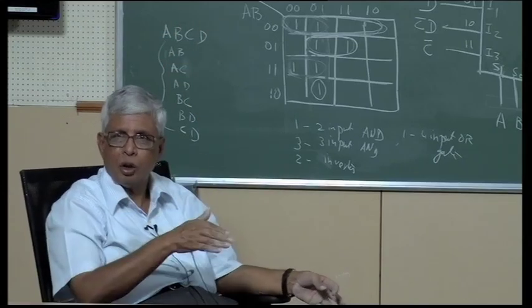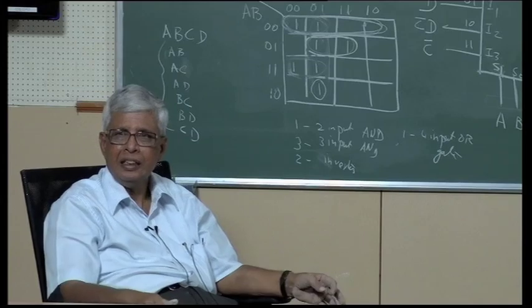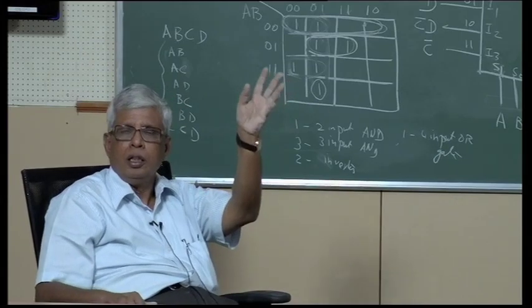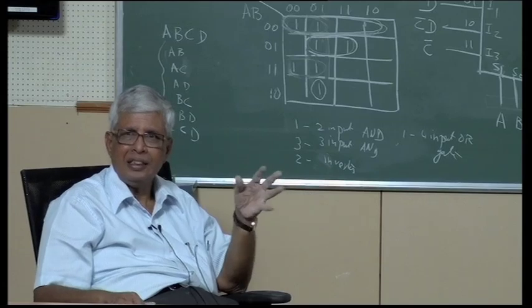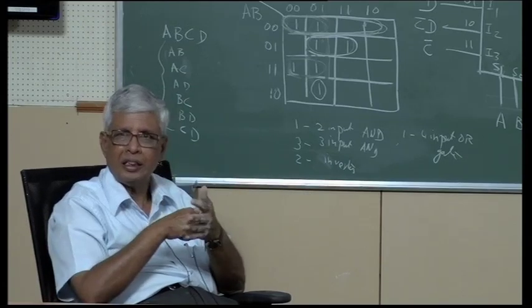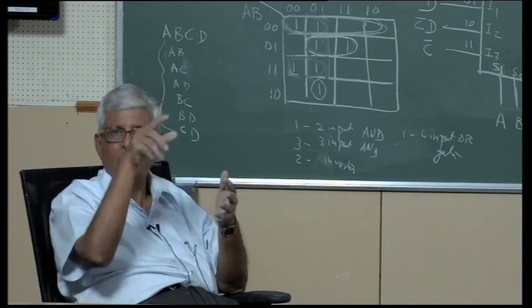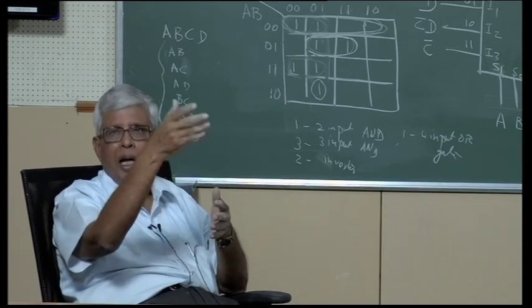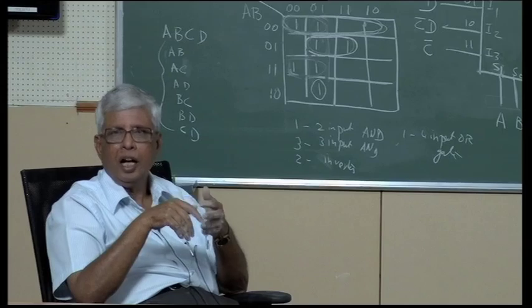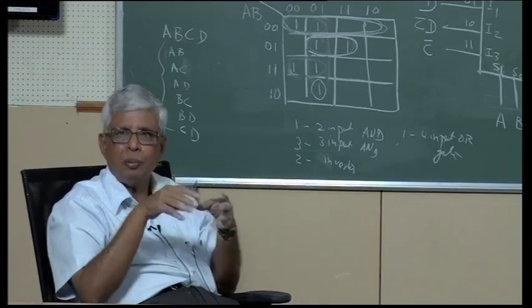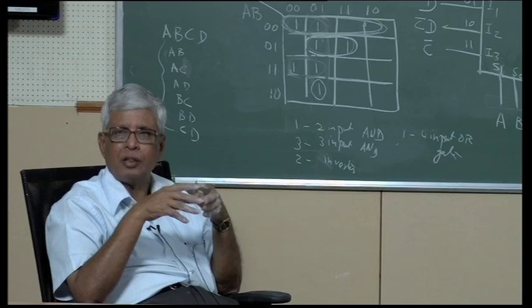So several sources, several destinations. One way is to run several lines. The other way is to have a mux, select one of the several sources, send it through a line, and then the output you send it to the appropriate destination. Of course, you need to run some selector lines from here to here, but that will be very appreciable only when the number is very large.